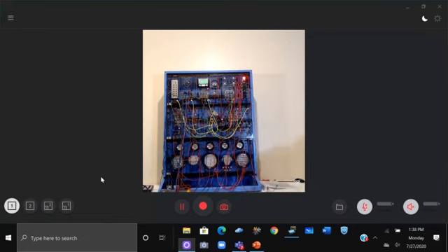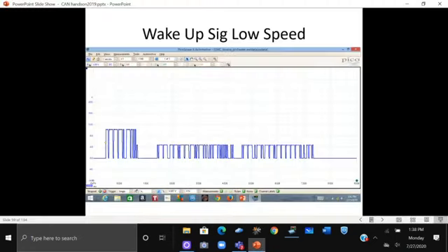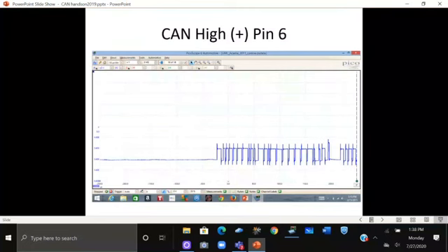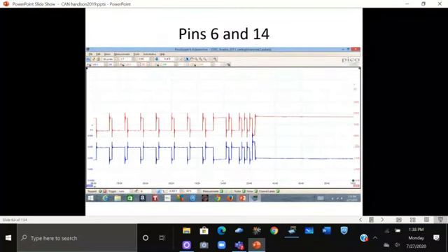The key here is to have the students recognize that once the signal is awake, then if we put CAN high and CAN low together, and we get them close enough, we will have a mirror image if the CAN bus system is in good shape. If there's a problem with the CAN bus system, then I showed you, you wind up with not a mirror image. It may track and follow one another, okay, but it's not the same thing.